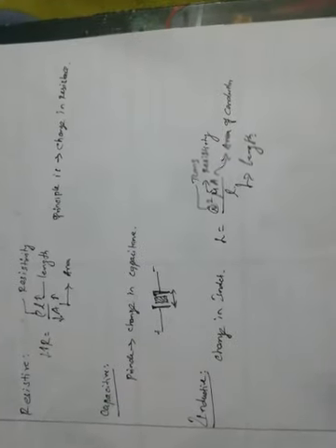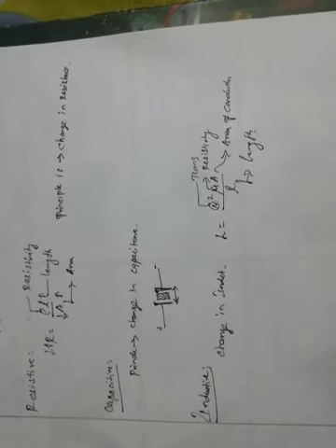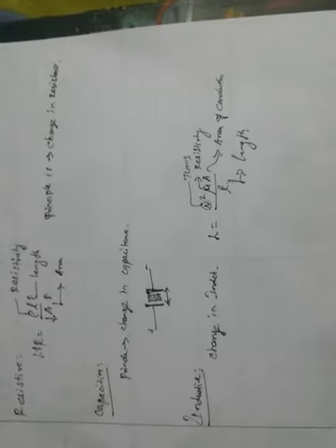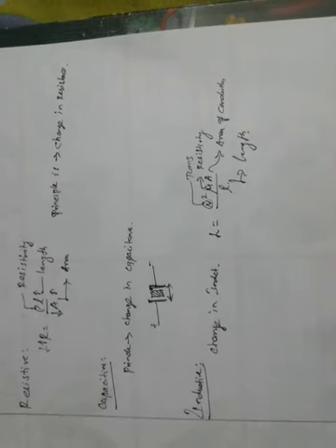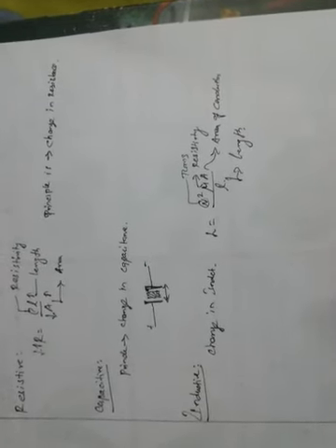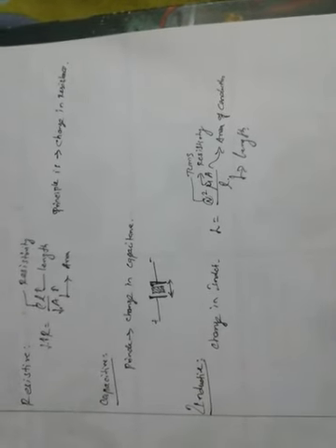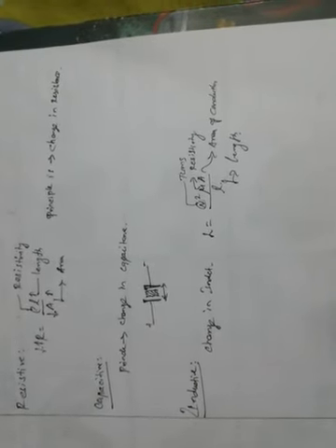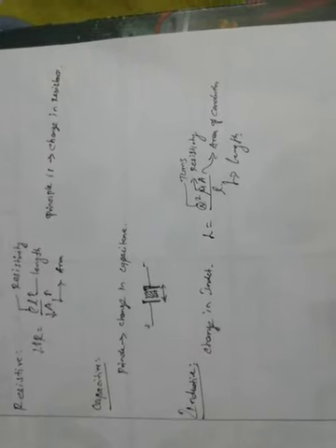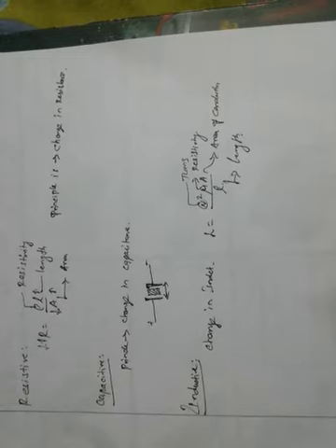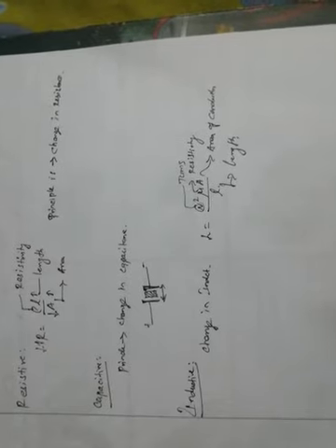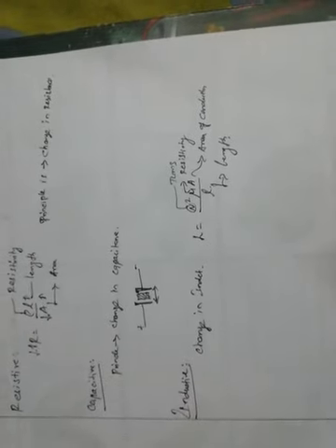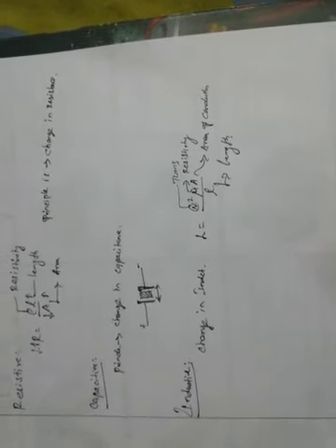Inductive transducers include the magnetic circuit transducer, the reluctance pickup transducer, the differential transformer like LVDT, the eddy current gauge to measure the eddy current in the circuit, the magnetostriction gauge to measure magnetic fluxes, and the Hall effect sensor for the purpose of measuring current. The applications of inductive transducers are to measure pressure, displacement, vibration, positioning of a system, force, thickness, sound, magnetic flux, light or radiation.